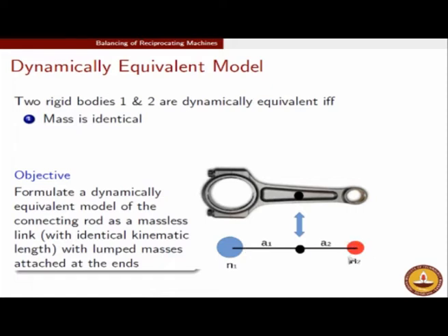Just like in weight training, in your weightlifting you would have the masses only attached at the ends of the rod. In comparison to the masses attached to the ends, the rod itself is massless. It is not that the mass has gone to 0. If you take a beam balance and measure the mass, definitely there is some mass. But in comparison to the masses carried by the ends, the rod appears to have very negligible mass. So, at this stage we would like to make a simplified model of the connecting rod, which is as follows.